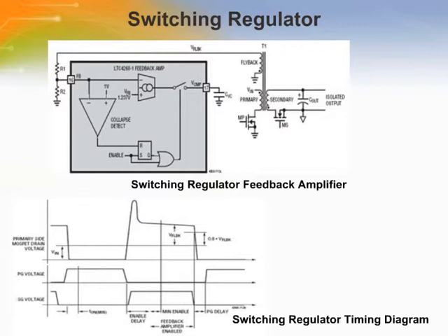The LTC4268-1 has a unique feedback amplifier that samples a transformer winding voltage during the flyback period and uses that voltage to control output voltage. The internal blocks are similar to many current mode controllers. The differences lie in the feedback amplifier and load compensation circuitry. The logic block also contains circuitry to control the specific and special dynamic requirements of flyback control.